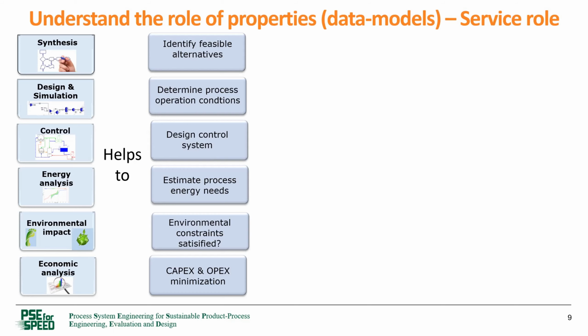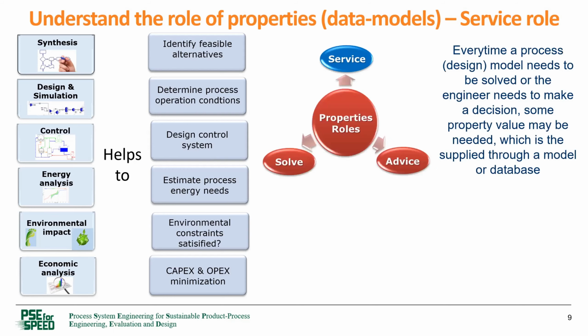So then what is the service role? This is the most common role of properties that people associate with, and probably that's why sometimes they don't respect the property thermodynamics that much, because what happens here is that whether it's the designer or the simulation model, if a property is needed to make a decision, one says, okay, I have this compound or a mixture of compounds at this temperature and pressure, I need a density, or I need the heat of vaporization. And then the property model gives that value. So that's what I call a service role.